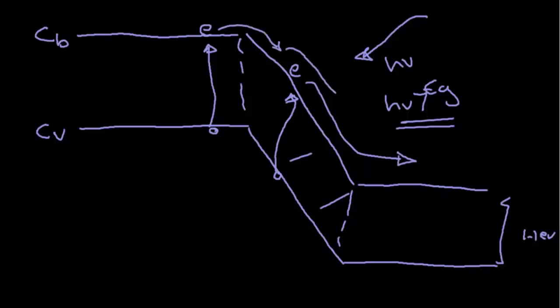That's why it's going to move to its lower potential energy, and the hole here will move up. In the absence of any light, there will be a small current, which is the reverse saturation current, and this current will be enhanced by the incident light because we will have additional photocurrent.